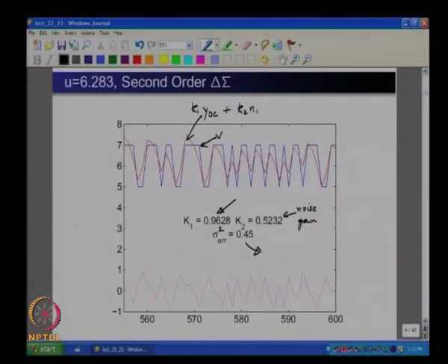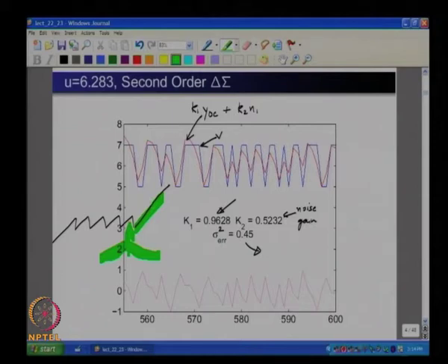So the quantization error transfer curve will probably look like this, and right now the input is sitting somewhere here, and on top of it there is quantization noise riding. So you can see that when the shaped quantization noise really starts to become large, you will easily excite some part of the characteristic where the error is large. So it makes intuitive sense that the mean square value has gone up from delta square by 12.